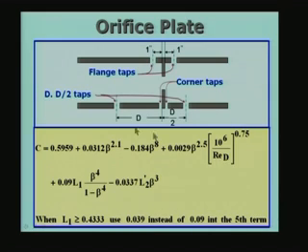Because the Reynolds number is not known, when you want to measure the flow rate, we do not know the velocity, therefore we do not know the Reynolds number. So this may require a little bit of an iterative procedure, because the Reynolds number has to be guessed or taken as some value, and then you find the velocity, and then find the Reynolds number again, and so on. That will require a little bit of iterative solution.